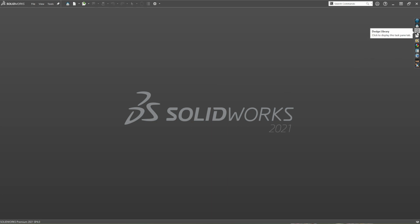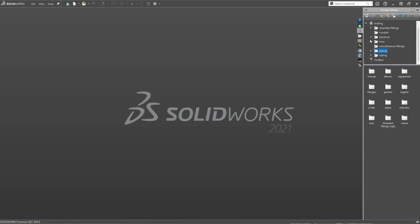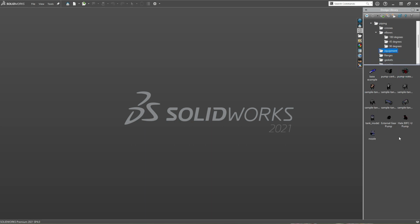Now let's check if the part is included in the design library. Go back to the design library panel here on the right side of the UI, and then in routing, go to piping, and then select the equipment subsystem. Now you can see we have added the external gear pump into the standard library system. So now we can use this pump for our piping design project.